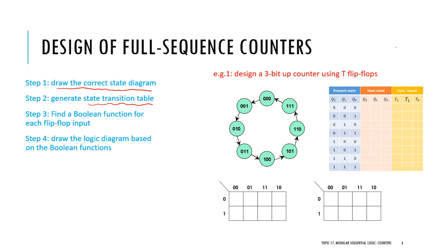Then we find a Boolean function for each flip-flop input. Once we have these Boolean functions, we can draw the logic diagram to realize the logic circuit.